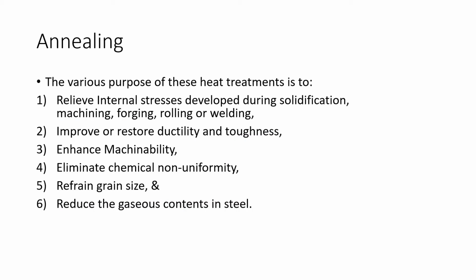The purpose of this heat treatment, annealing, is to relieve the internal stresses developed during solidification. Annealing is one of the heat treatment processes to relieve the internal stresses developed during solidification, machining, forging, rolling, or welding, to make our material better for machining, forging,